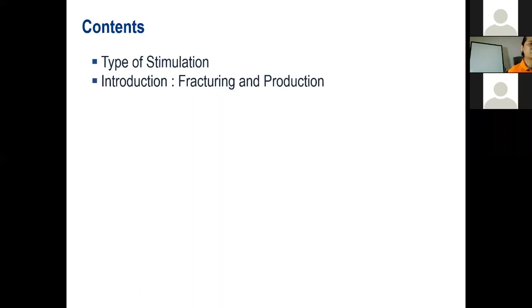Okay, type of stimulation. When I give a class to next training, Schlumberger or to IATMI, during that 5 days a lot of topics are covered, but I try to give some introduction here on fracturing for your basis to understand what a fracturing is in the oil field industry, because in the 5 days you go into detail on the fracturing geometry optimization, what is the best frac length, width, and everything, and as well on the data frac analysis or mini frac analysis.